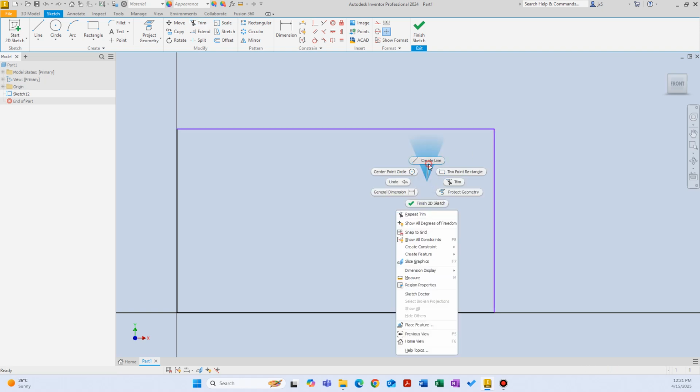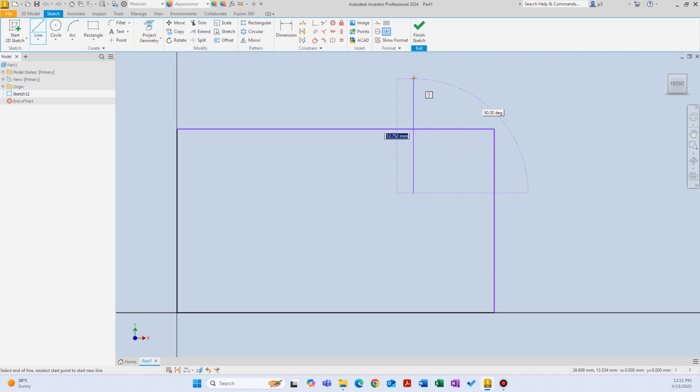To explain what I'm talking about better, let's create a vertical line here. Now this vertical line and this horizontal line intersect here. So if I click on this line and delete, again, it deletes the entire line. Let's undo that and bring that line back. But if I trim, now it cares about the nearest boundaries. It doesn't care about the whole line. So it deletes the section of that line between this vertical line here on the left and the vertical line here on the right. So now I can even trim this section and delete the other side of the horizontal line as well. Or let's undo that.